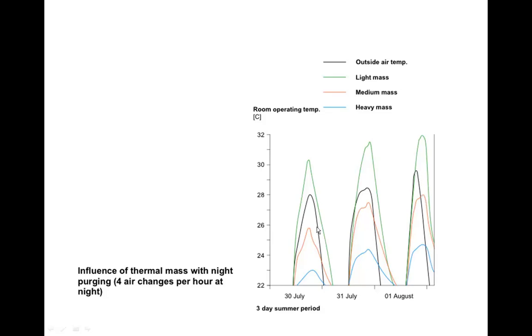So you're getting this huge benefit, and it's a very, very effective passive sustainable design approach. Passive, because it's not doing anything. Your building needs a structure, it needs a floor, and it's got no controls, it's just a big lump of concrete, making a huge difference.